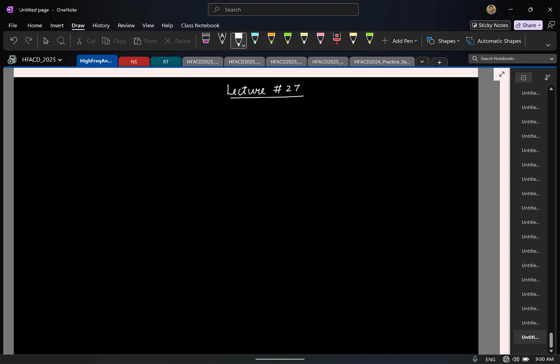Okay, let's start. So in the last class we briefly saw how things are made on a CMOS process, and we essentially saw that in practice if you have multiple identical components there will be mismatch among the components, and we have both random and process variations. So to make sure that point is clear, let us say you have one particular chip with 1000 identical components, let's say resistors, and if you plot the values of all the resistors and look at its distribution, it will be Gaussian like this, centered around the mean value R0. So this variation within a particular chip is what we call random mismatch.